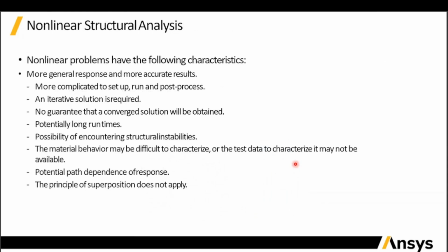It is more complicated to set up, run, and post-process. An iterative solution is required for this simulation, and there is no guarantee that a converged solution will be obtained. Nonlinear analysis takes a long run time, and there is a possibility of encountering structural instabilities while running it.